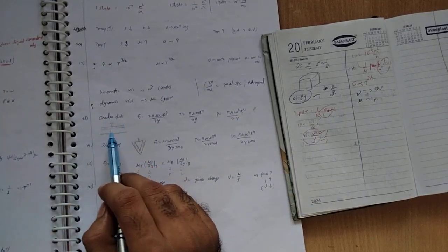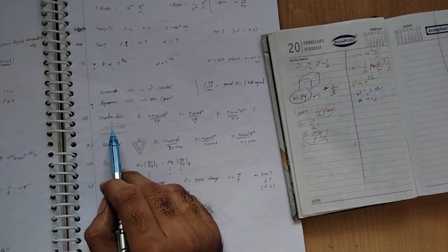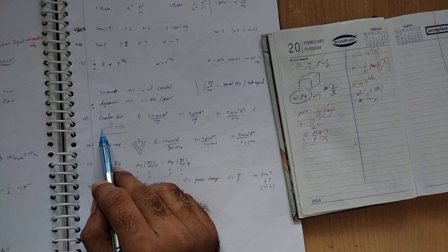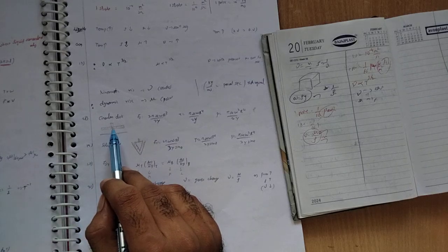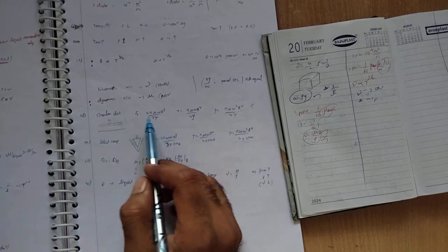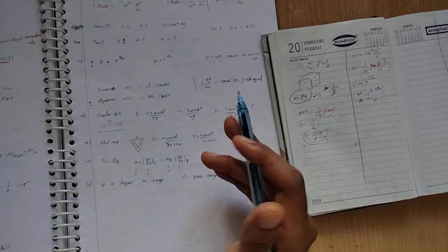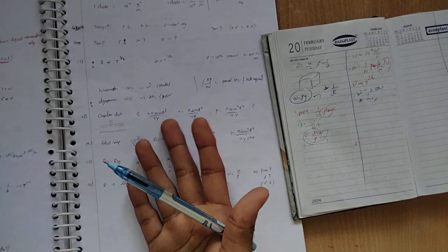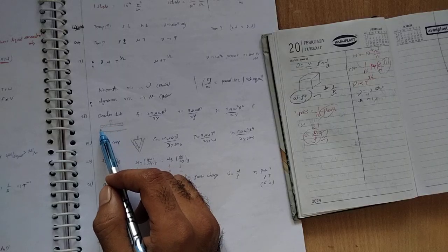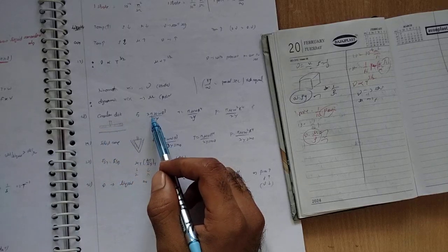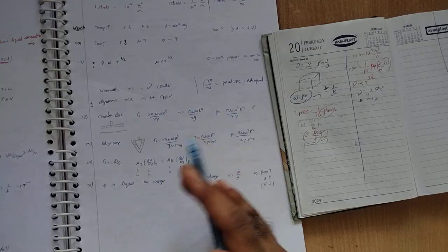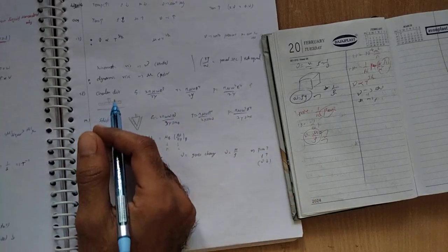For the circular disc, I already explained this. In this the velocity itself will vary. Here it will be 0 velocity, but here is the maximum velocity. Depending on each and everything, it will differ. So shear force equals this. The torque will also vary a little bit, since it depends on the outer radius, so the outer will have maximum torque: 2 pi mu w R cube by 3y. While I explain the problems, I'll tell this.